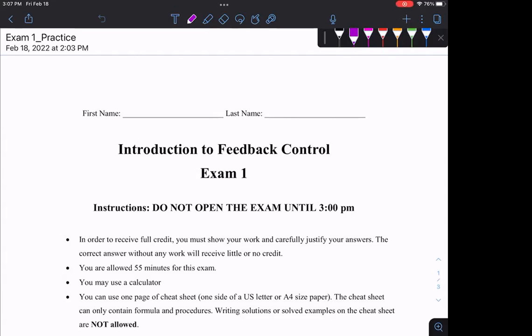So what does it mean? Let's say that you don't want to remember how to do feedback loop reduction. The equation is, you have G and H, G is in the direct path, H is in the feedback path. You write T, your transfer function, is equal to GH over 1 plus GH. There is no example of, let me put one S or one number and I can do it, to bring with me. So you can bring this equation, you can bring this formula, but that's it.